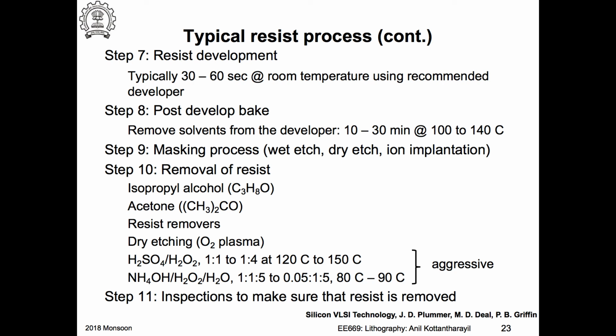But typically the photoresists are thin, maybe a few hundreds of nanometers. Thick photoresist can be maybe a micron, 2 micron, but it's not necessarily enough to absorb all the light, because it has a finite absorption coefficient. So the light that goes through will get reflected.